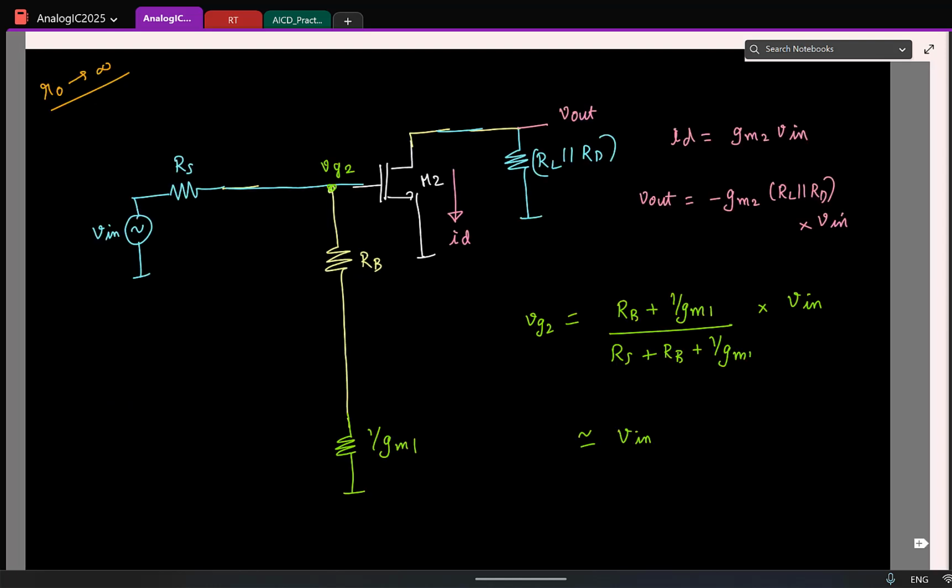Now, interestingly, the drain current in the transistor flows between which and which terminal? Drain and source, right? If I had to change this current, what voltages should I be changing? VGS. So I can change the gate voltage or the source voltage. Remember, the mechanism I use is I sense the drain current and then change my VGS.